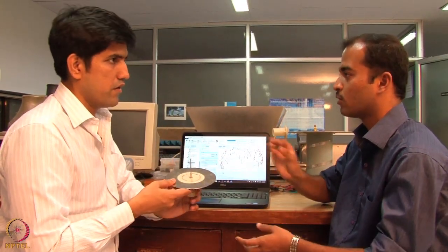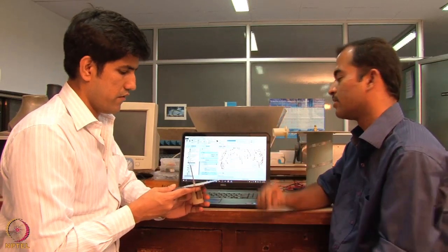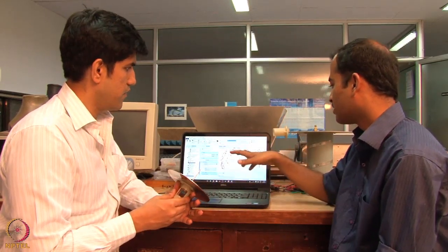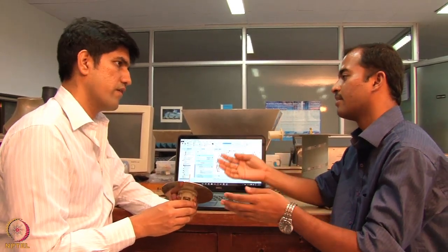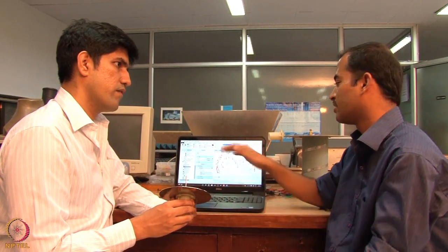So the Gaussian pulse excitation you mentioned is done in CST. Also, we can apply the scattering boundary condition in this solver. But the scattering boundary conditions need normal incidence of the wave, so that gives a bit higher reflection than the perfectly matched layers. Okay, so the perfectly matched layer solves the problem of reflection issues.